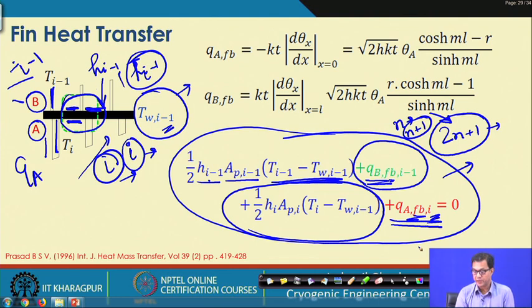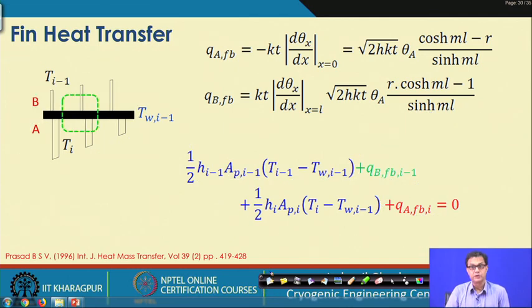and those become algebraic equations. We then need to solve them to find the wall temperatures as well as the fluid exit temperatures, and that is exactly what we were looking for to simulate the plate fin type heat exchangers. Once we know the exit temperatures of the fluid streams, we would be able to calculate the heat duty of these brazed aluminum plate fin type heat exchangers.